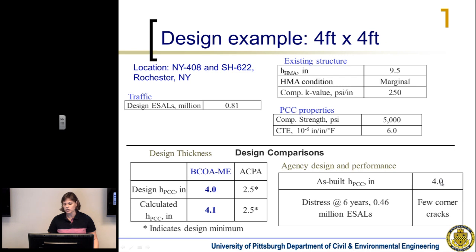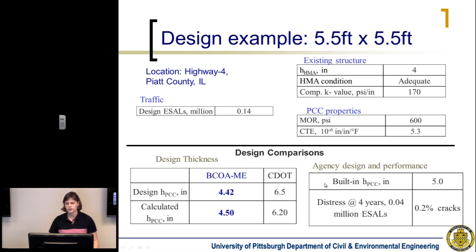Okay, what was actually constructed was 4 inches, and here we're about halfway through, a little bit more than halfway through the design life. We have a few corner cracks, so it seems that the BCOA probably did or would predict a reasonable design for this project.